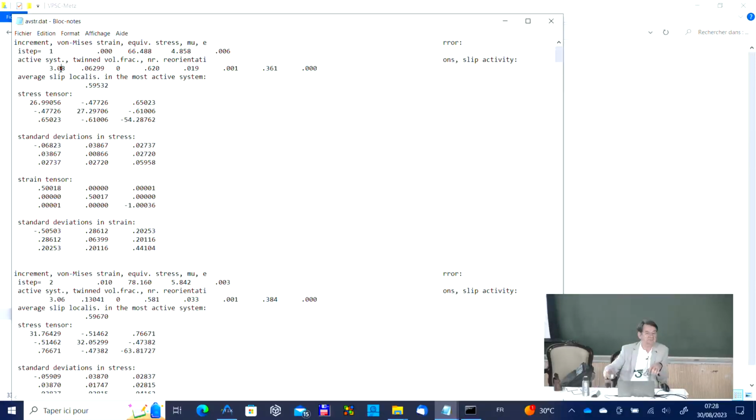You might ask how then the crystals could be deformed only by 3. But you see, we set actually this alpha tuning parameter very low. And if you would go to 0, you would end up with the static state. There would be only 1, probably slip system activated for the non-symmetric orientations. Only 1.